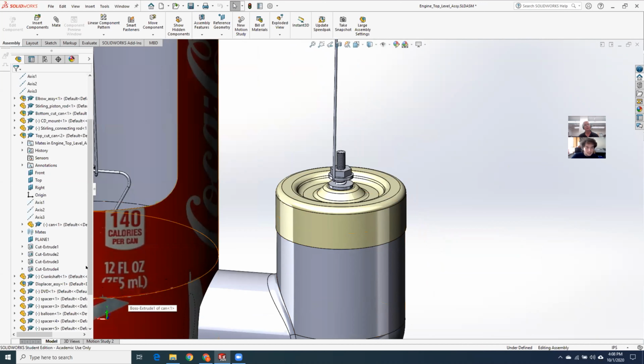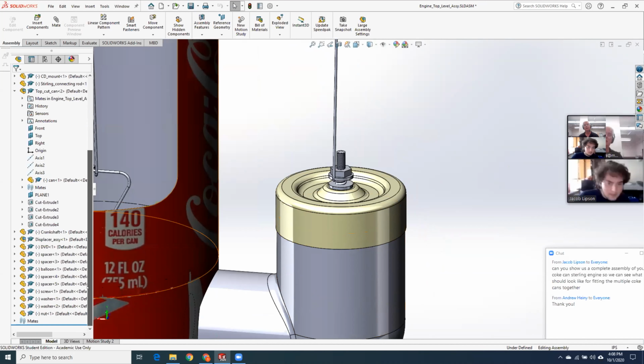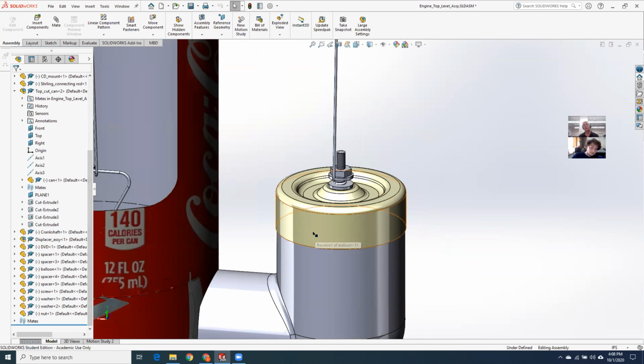All right, so what you got there is a screw, nut, spacer. Basically, you just want to bolt through the balloon. Everybody that's tried to glue to the balloon so far has had the glue rip off. So I just put a bolt through and I just clamp it with 2 washers. And that gives you a nice airtight seal.